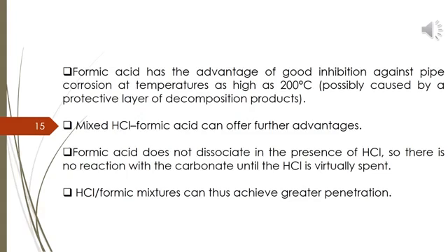Now mixed HCl and formic acid can offer further advantages. The mixed proportions give further advantages. Formic acid does not dissociate in the presence of HCl, so there is no reaction with the carbonates until the HCl is virtually spent.